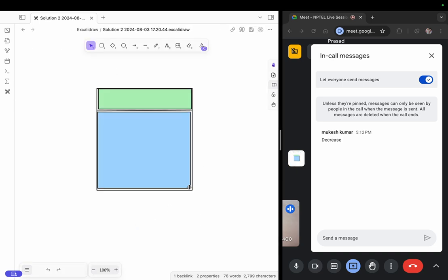So when you say the pressure at the bottom is rho g this side plus rho g this side, it means the pressure difference between this point A somewhere on the top and point B somewhere on the bottom. The pressure difference between these 2 points is rho g h. So this is what we are calling gauge pressure. The reference is with respect to A. Let's say A is a reference point and P is a point at which I am measuring the gauge pressure.